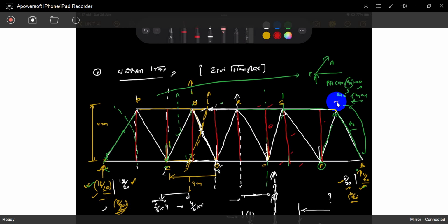Sir, why is it placed, sir? It's placed because of buckling. These two members may have a chance of buckling. So to reduce that buckling effect, we can provide another member like this, but these members don't take any loads by truss theory. If you see this type of truss also, this is also a Warren truss because this doesn't take any loads. Are you understood? That you also have to observe. This is also a Warren type. This doesn't take any loads.